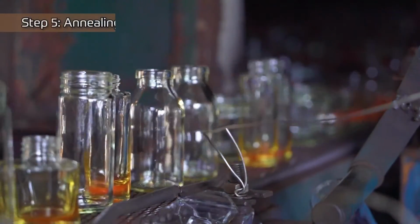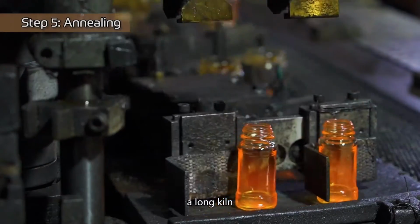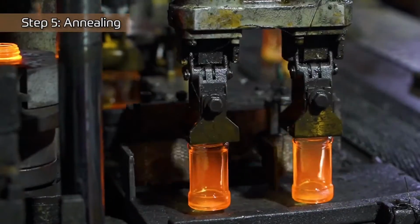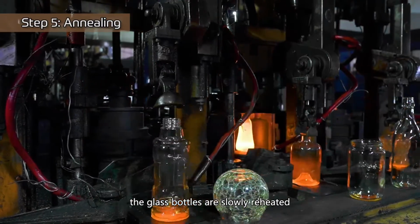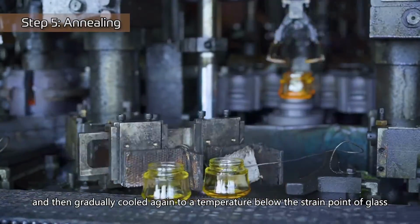Step 5. Annealing. The glass bottles are moved into an annealing lehr, a long kiln. In it, the glass bottles are slowly reheated and then gradually cooled again to a temperature below the strain point of glass.